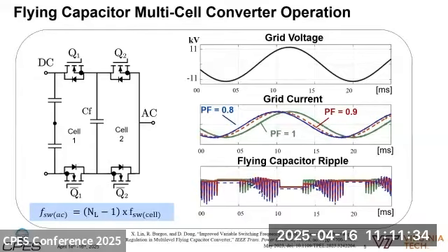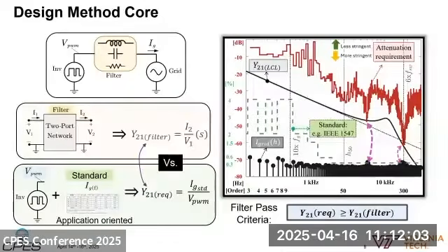In this converter that David just presented, we have a variable switching frequency scheme: every time we reach a limit for the voltage ripple, we toggle to a higher switching frequency. But we only do that in certain periods of the fundamental frequency. That way we avoid increasing the switching frequency too much. But this has some consequences for the filter design, which we are going to see soon. But before we go there, I would like to first introduce the method.